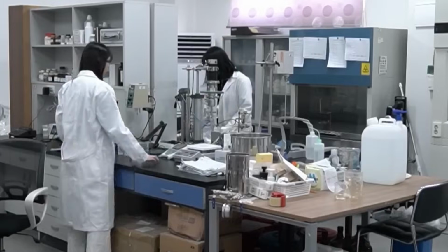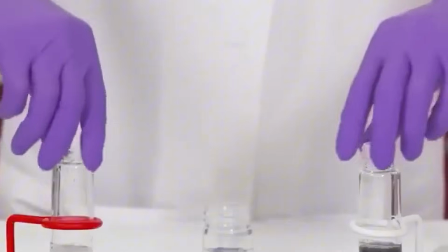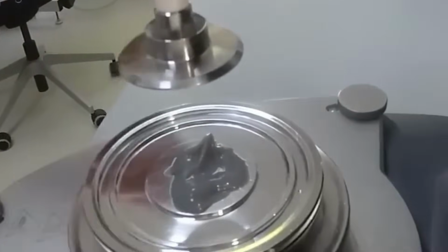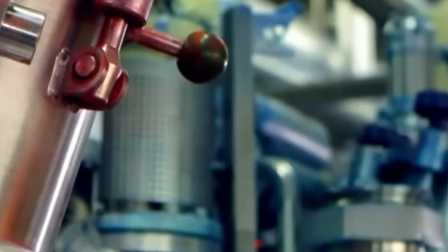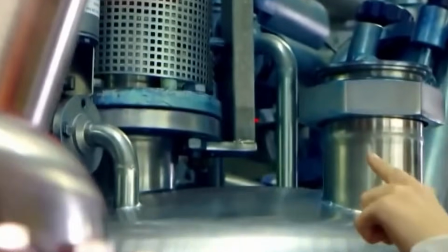Flavoring oils like spearmint or peppermint are stored in sealed drums and introduced through small volume dosing systems equipped with peristaltic pumps. Flavors are highly concentrated and dosed between 0.3–0.7% by weight. The addition is carried out under vacuum to prevent volatilization.